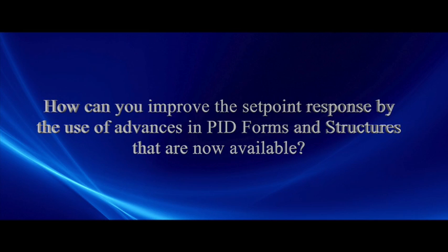But the problem you get into is if you did use derivative action with a series controller, as you add more rate time, it counteracted the other modes and reduced their effect, so you didn't get into trouble. So you can actually set a rate time as large or larger than the reset time in these older controllers. And remember, when I say reset, I'm saying seconds per repeat. So you've got to think of what the reset setting was in terms of seconds per repeat.